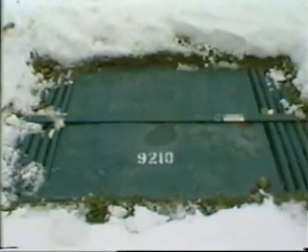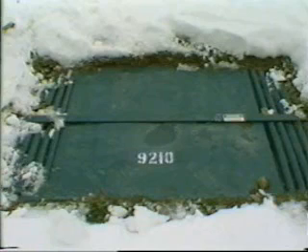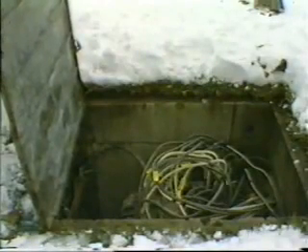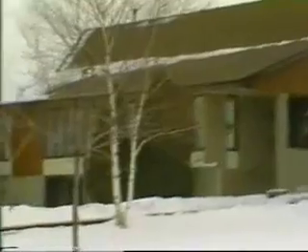One particular type of underground transformer is the submersible or subsurface type. These units are designed to operate in an underground enclosure with a top grate to allow the transformer to be ventilated. These transformers are normally used to serve underground residential or commercial loads.